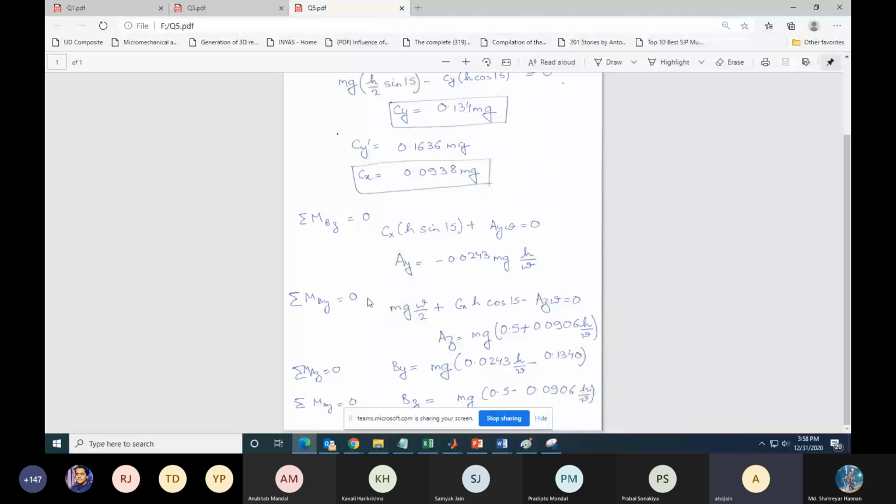Then I will get different values. If I take moment about point B about the Z axis, the reactions at B and Az will pass through, giving me 0. So I get Ay directly. If I take moment about point B along the Y axis, I'm getting Az, and so on.